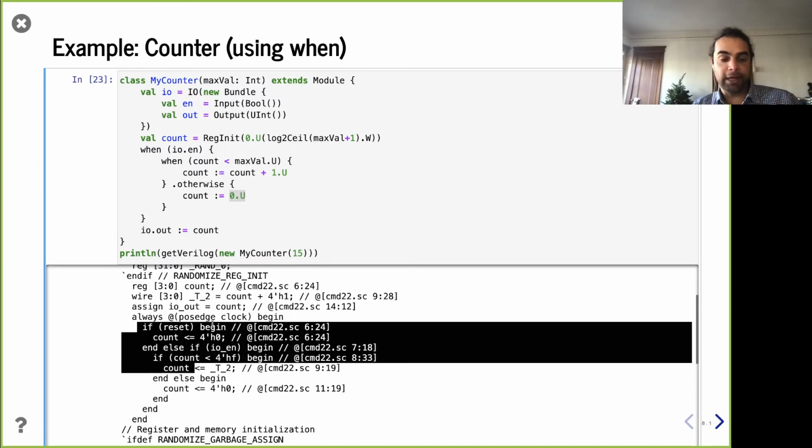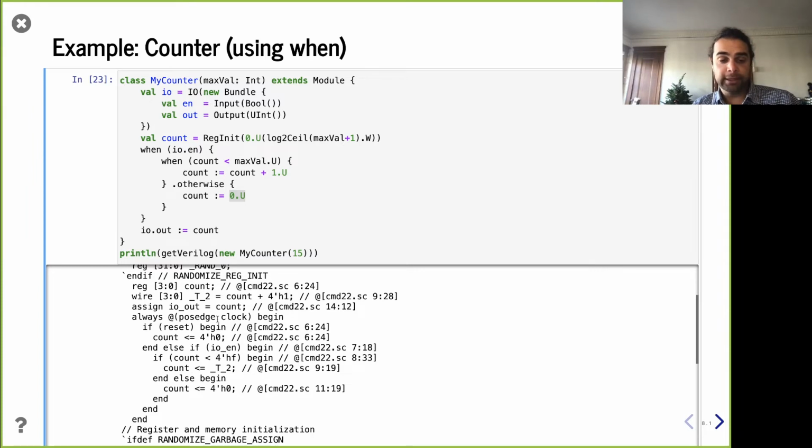For those who don't know Verilog, what the always block says is, hey, there are some conditions, so whenever this evaluates, evaluate this assignment list, do the internals, right? So for a flip-flop or register, you only want to change once per cycle. So the way you do that is you say, hey, when the clock is on this positive edge, do this inference and it infers the register. You're not required to have positive clock in here, right? You can also have arbitrary signals in there, in which case it's going to evaluate at other times, and you can even do pure combinational logic with always. So yeah, always is complicated.